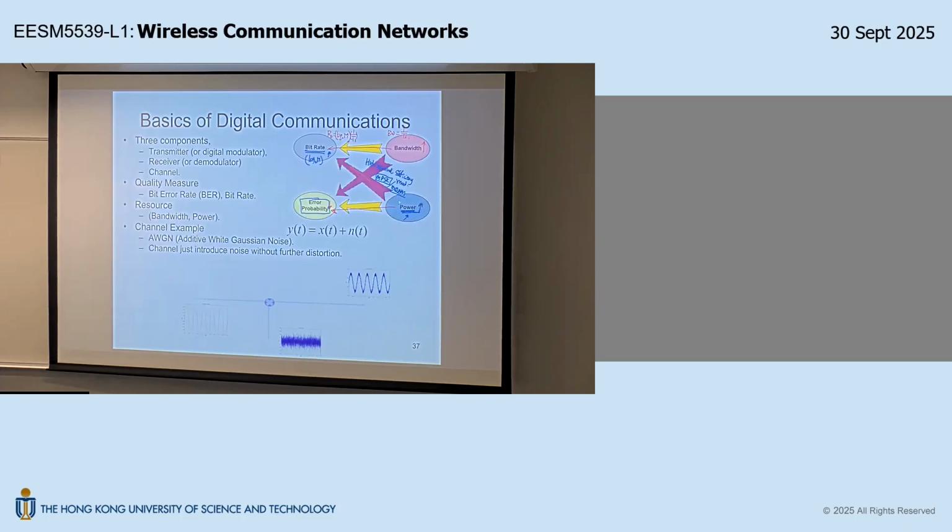That's why if you look at practical designs like Wi-Fi, 3G, 4G, 5G, and the modulation levels in these systems, you'll come across BPSK, QPSK, 8PSK. But when you go for 16, you don't see 16 PSK. You only see 16 QAM onwards, okay? So when M is larger than 8, usually people will just give up PSK and go for the QAM family for this reason, because the QAM family will be more efficient.